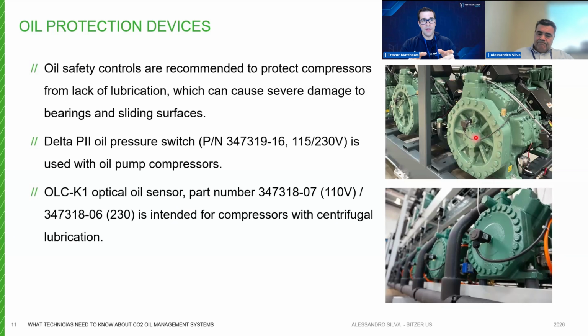Yeah. So there, a technician can take the pressure from the oil pump pressure. Can you see that on there, where you take the oil pump pressure? Can you highlight it? Yeah. And the crank. And if you do that differential there, that's how you would tell if that strainer's plugged, correct? Exactly. Yes, that's the reason.